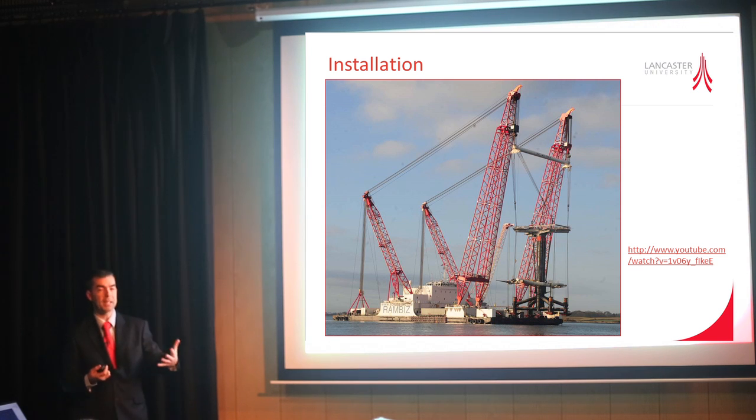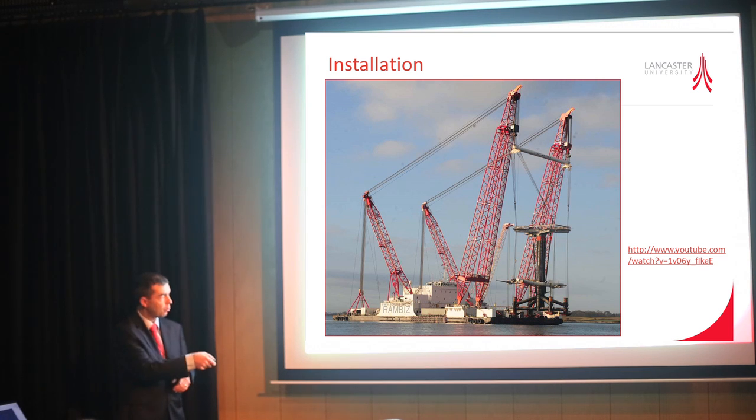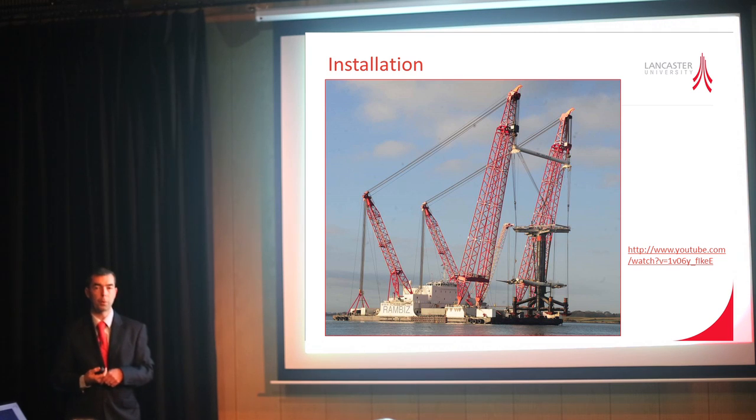So it was a complete year before they were able to reinstall the turbine, at which point they had a design change. Rather than rely on just a single monopile, to make the foundations easier, they split it out to this arrangement where they've actually got 4 smaller foundation structures to support the turbine rather than one large one, and it made installation for them far easier.